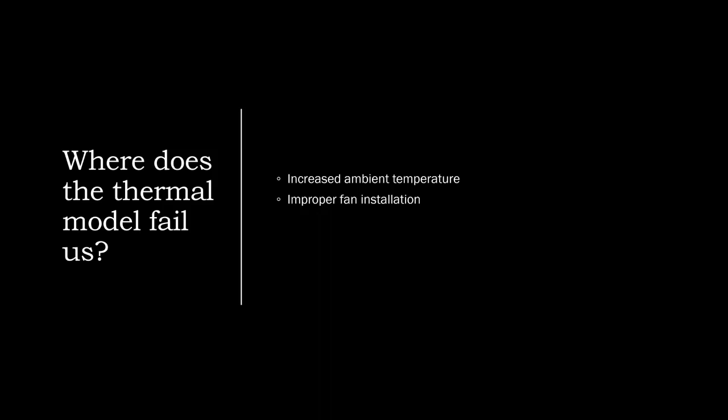Additionally, I spoke to somebody about a month ago who had this happen, and it's a very unfortunate situation. But the motor rewind market is a competitive place, and sometimes there is turnover in these type of shops. And there was a fairly substantial motor that went into a paper mill, and after it was rewound, the fan was put on backwards. And the thermal model, of course, will not account for that. Thermal model looks at the current going into the motor, and that's it. And it is relying on the nameplate information that is input into that motor. And the nameplate information is dependent on that fan being properly installed.